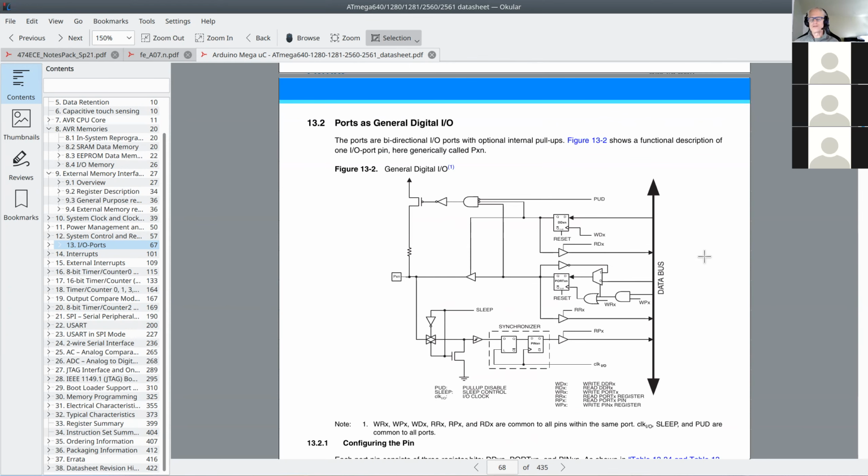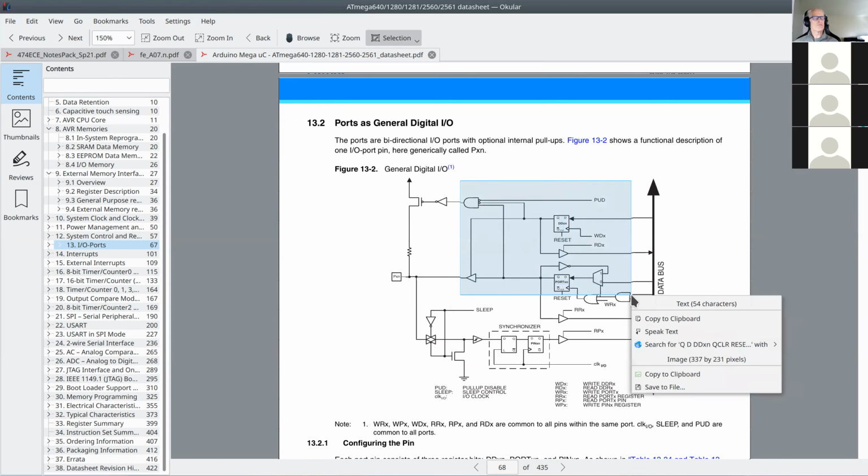This is the real thing under the hood. There's much more, okay? But I'm going into detail because you're going to use pins. You're using pins already, and you're going to do a lot of things with the pins on these chips. So for every one of those 50 pins or whatever it is, you get this. And I'm not even going to tell you everything about it. I don't even understand everything about it. But we just went over this part, okay? That is the pull-up resistor. And this is a bunch of logic that determines if the pull-up resistor should be set or not.